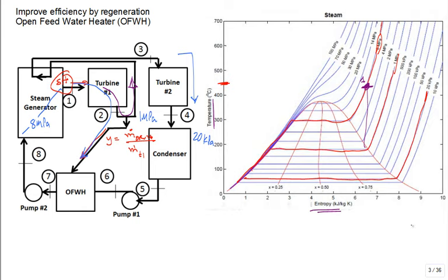Actuality is going to be kicked over. There's going to be some higher entropy going out of that insulated turbine because of irreversibilities. And this, so you would walk around this property diagram. Okay? Does everybody feel comfortable they can walk around a TS diagram, put all the states on for a cycle?